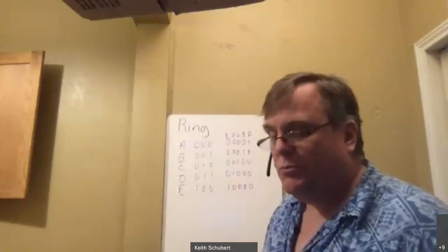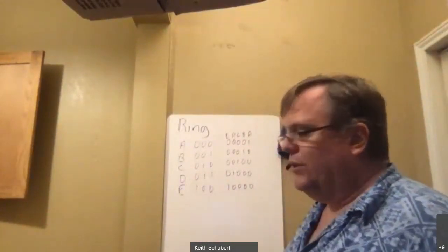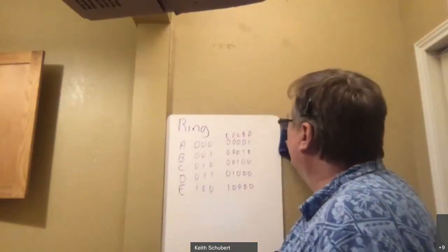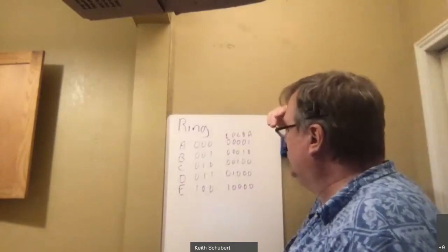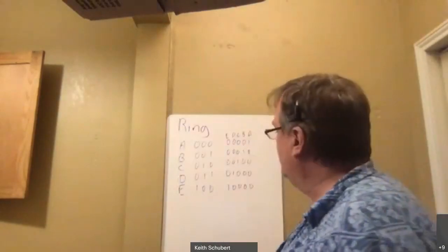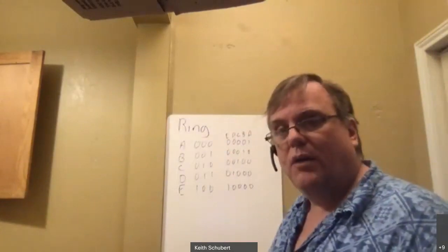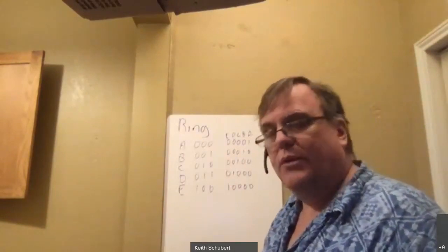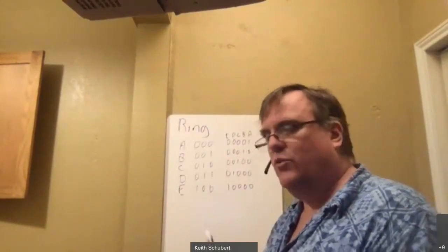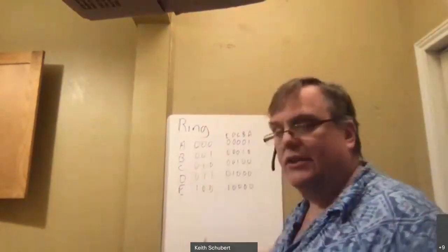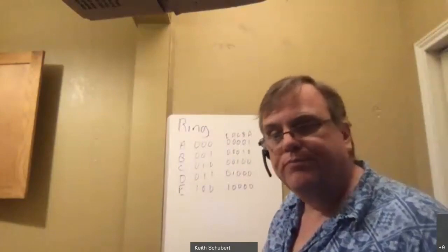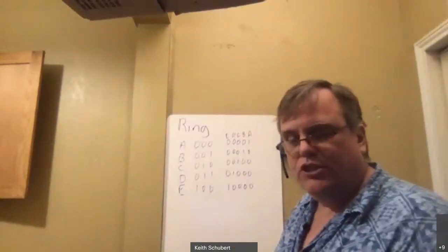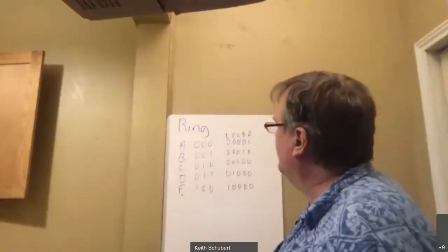For something small like this, you're pretty much guaranteed it'll be fine. But when you get to larger numbers, it gets more and more challenging to make that happen. So if you get really big designs, or if that design happens to cross a clock boundary, sometimes you have to cross that clock boundary because your system deliberately has to stand between. Maybe you've got one area running on a fast clock and one running on a slow clock, and you have this state machine that operates between the two. So I might be forced to be on a clock boundary, and then I have to be very careful to do the checking, and even assertion checking becomes really difficult under those cases.